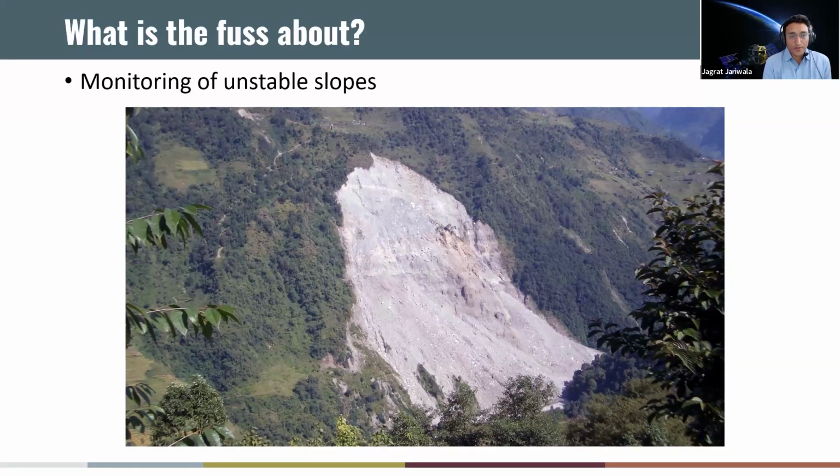Now, monitoring slopes. That's a very similar story here as well. InSAR's penetration in monitoring and providing solutions for landslides and unstable slopes is also quite high. Folks have used InSAR to figure out the actual extents of the landslide, then use that information to figure out where their inclinometers, let's say, are going to go, the on-site instrumentation.